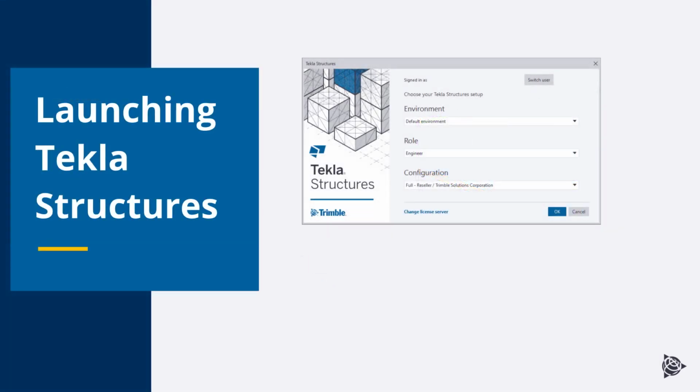When you open Tekla Structures, the first thing you have to do is to choose your setup. Environment means a set of settings and information specific to a company or region. It defines, for example, which profiles, material grades, default values, and connections you have available. You can load environments from Tekla Structures downloads.